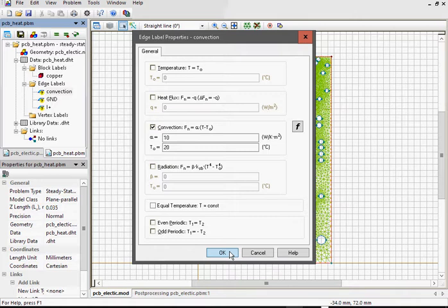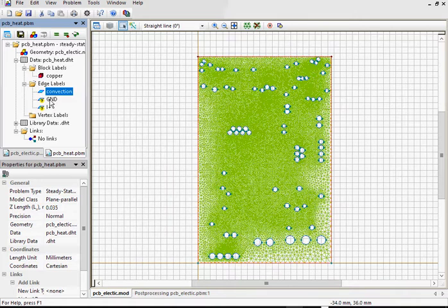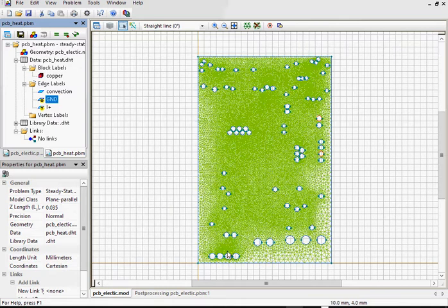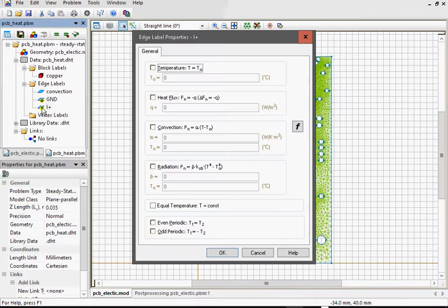Okay. There is no specific conditions to assign for the source and for the drain and for the holes, so I double click the label and do not enter any values and click OK. Now you see the label has the 0 mark, which means there is no physical properties assigned to this label and this label should not affect the results. The same for the E+ label.